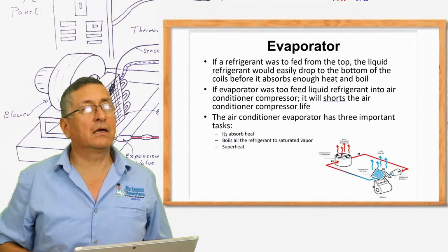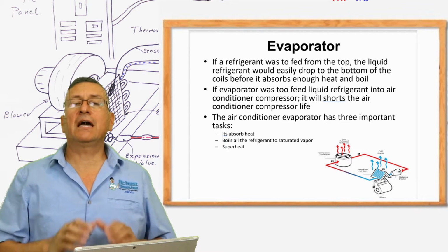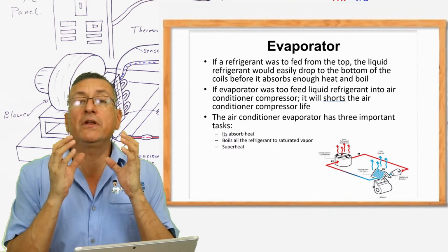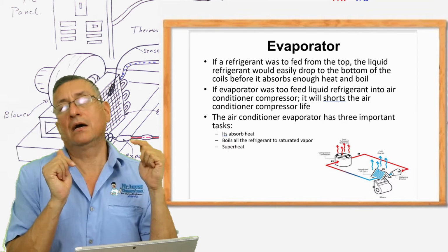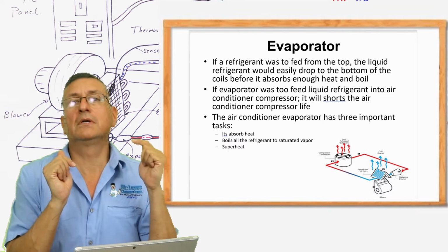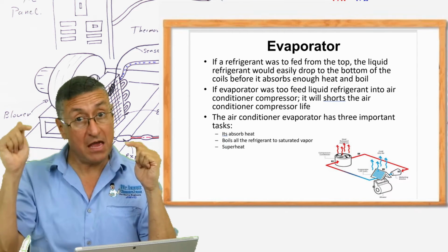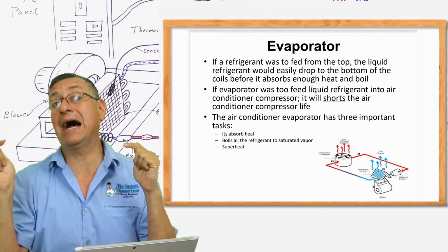I repeat, as in a previous episode, and I am going to explain later again, that the compressor receives the refrigerant vapor on one side, high temperature vapor, low pressure, but in the output is vapor supersaturated at high pressure and high temperature.